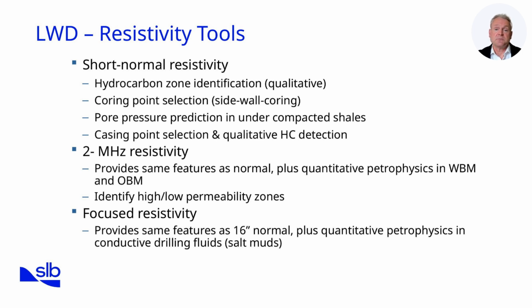Next, we have the 2 MHz resistivity tool. This provides the same features as normal resistivity tools, but goes further by delivering quantitative petrophysical measurements, whether we are in water-based mud, WBM, or oil-based mud, OBM. It is particularly useful for identifying zones of high and low permeability, giving us greater insight into reservoir quality.